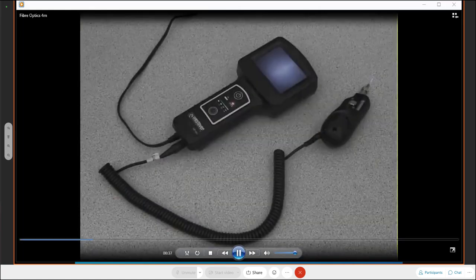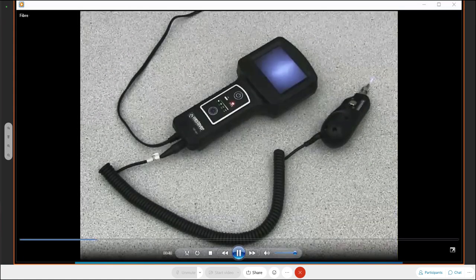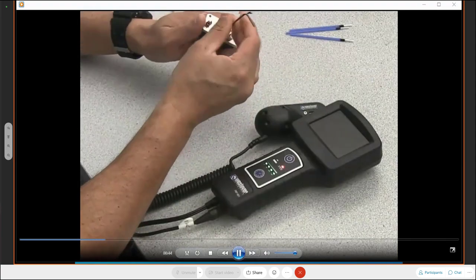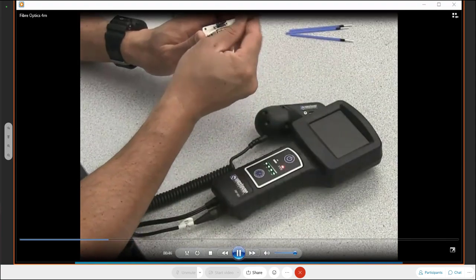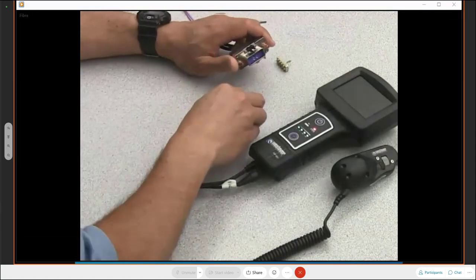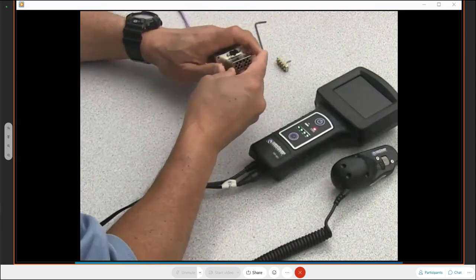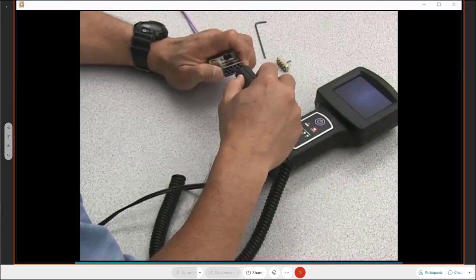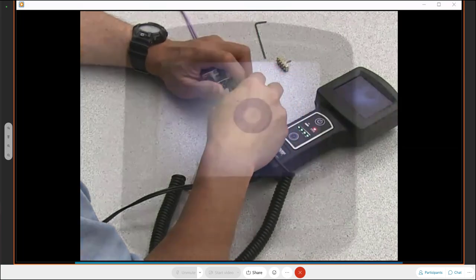There are two steps in this process: inspecting and cleaning. First, visually inspect the cable ends using an inspection video scope. Remove the alignment sleeve insert if needed. Install the inspection video scope probe to the end face to be inspected. View the fiber optic cable end face on the video scope screen with the probe magnification set to 200 times